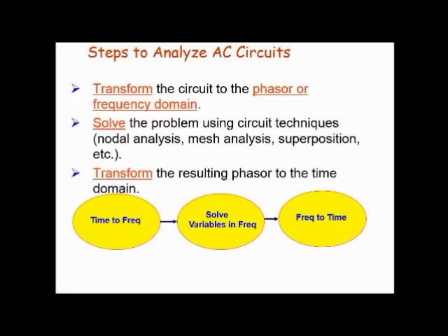Here are some steps to analyze AC circuits. First of all, you need to transform the circuit to the phasor or frequency domain. Then we need to solve the problem using circuit techniques like nodal analysis, mesh analysis, the superposition theorem, Thevenin's and Norton's. Then we have to transform the resulting phasor back to the time domain.